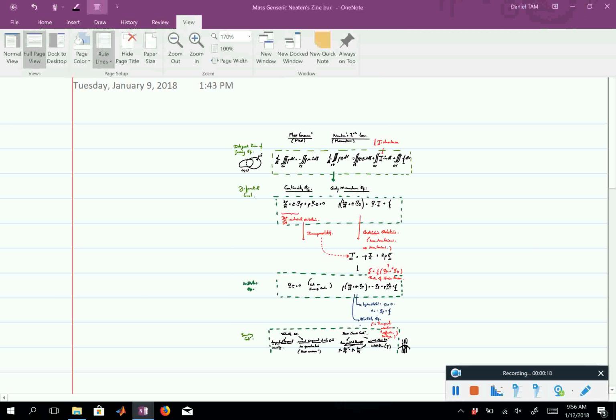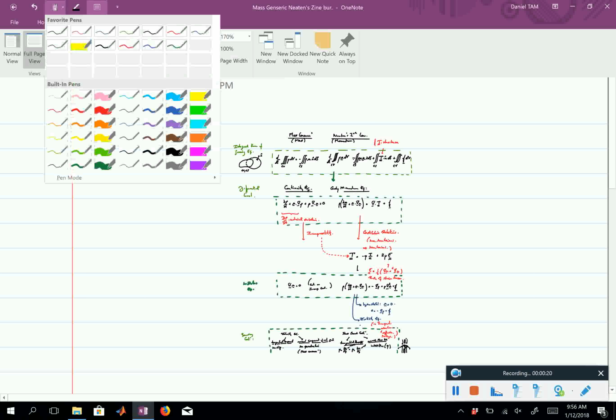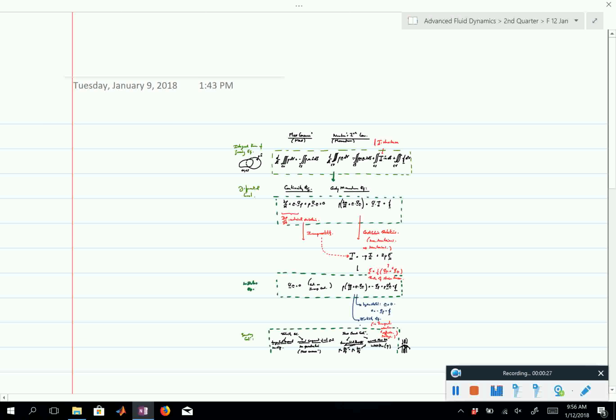Now, in most problems, before you attempt to solve the problem, what you will want to do is to simplify these equations. Everything we've discussed now is very general. The only assumptions we made from going to here to there is that we assume a material to be a fluid and not a solid, and then we assume that it was a non-Newtonian fluid, and we assume the flow to be incompressible. Those are the only three assumptions that we did, okay?